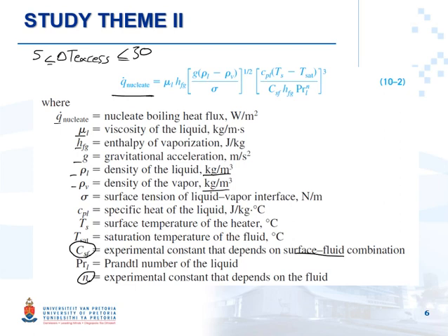Should I just read it at any temperature that I want? What do you think? Any idea at what temperature you need to read? For nucleate boiling, or this Q nucleate, you need to read the properties at saturation temperature.